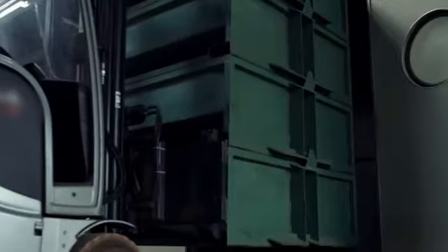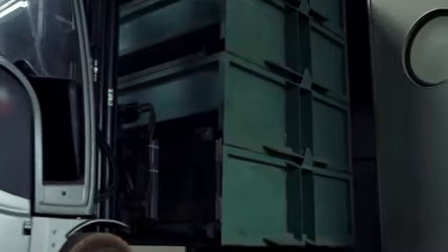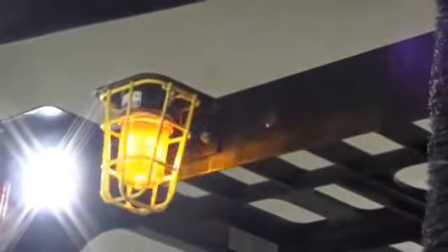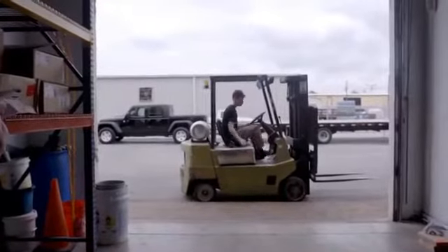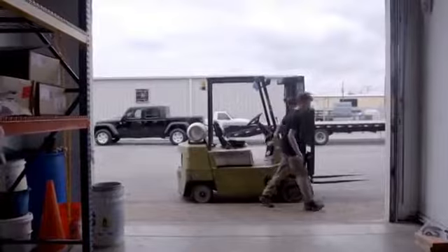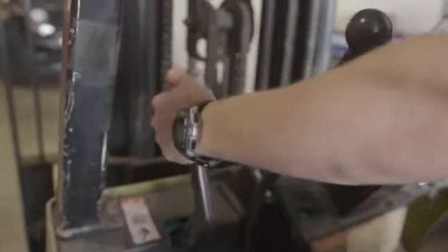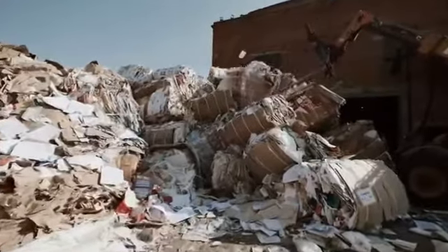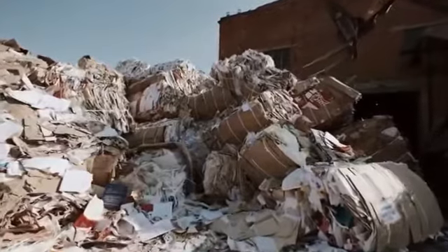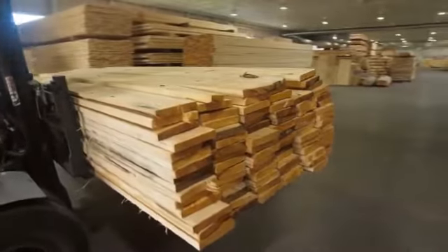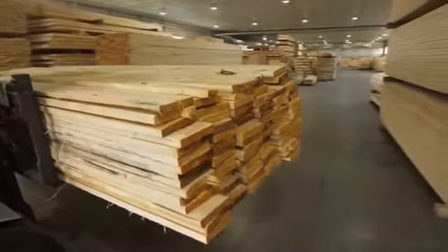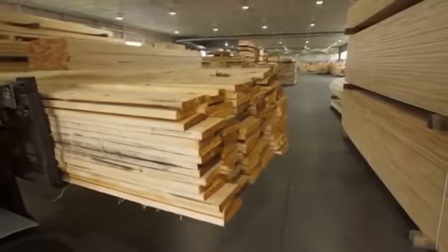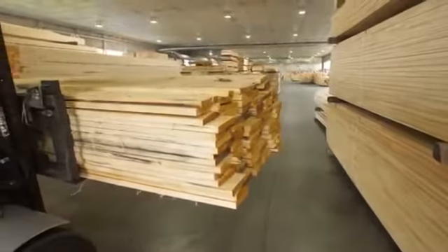Come to a complete stop before changing directions and use a horn or warning light to warn pedestrians when reversing. Do not park in unauthorized areas or block aisles or exits. Set the parking brake when stopping. Loading. Handling loads can present different hazards for different forklifts. Improper techniques or loading can cause a forklift to tip over, the load to drop, a collision, or other accidents.